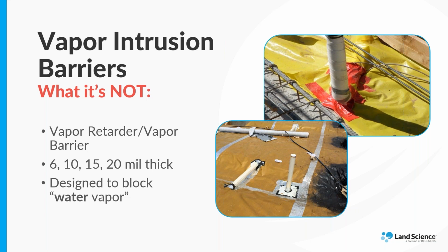Those that have been on site during an install may notice that the picture on the left looks a little strange. Is that a taped system with spray-applied material? Well, it is. The project was dealing with a variety of challenges, including trouble passing a smoke test. Ultimately, that tape had to be modified in order to meet regulatory requirements. Once the design changes were approved, one of our installers was called in to spray over the entire existing barrier in order to make a vapor-tight seal and pass the smoke test. It was a really great example of finding a unique solution to help a client meet some regulatory requirements.